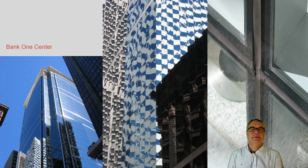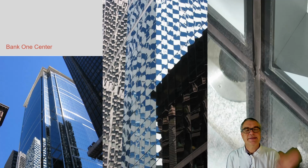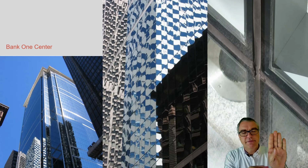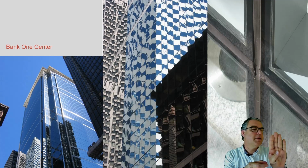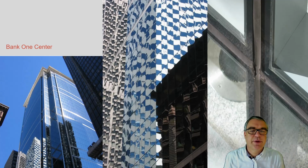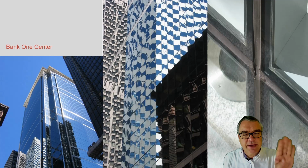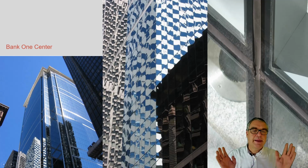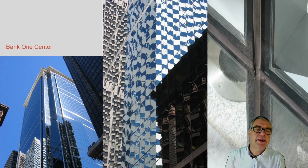Structural glazing, that idea means that the glass itself is laminated onto a substructure, and it's laminated with silicone, so it's actually not the glass which is structure, it's the silicone which is structure, so we should better call it structured silicone, but history creates certain names. This structural glazing delivered the opportunity to create these shapes, which entirely disappear in the surface.